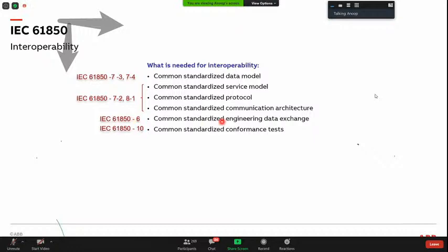engineering also. For example, there are two devices that both say they comply with the IEC 61850 standard. Siemens says I have 61850, ABB says I have 61850. But make them talk to each other, you cannot. It's not plug and play like Bluetooth, where you just switch on Bluetooth and connect.